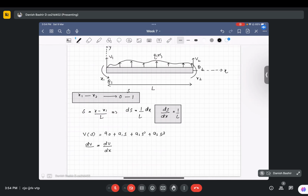Our dv by dx will come out to be dv by ds, because v is a function of s, multiplied by ds by dx. Okay, so if you see, ds by dx is already 1 by L, so we will write ds by dx to be equal to 1 by L and differentiate this function with respect to s. We will get a1 plus 2a2s plus 3a3s square.